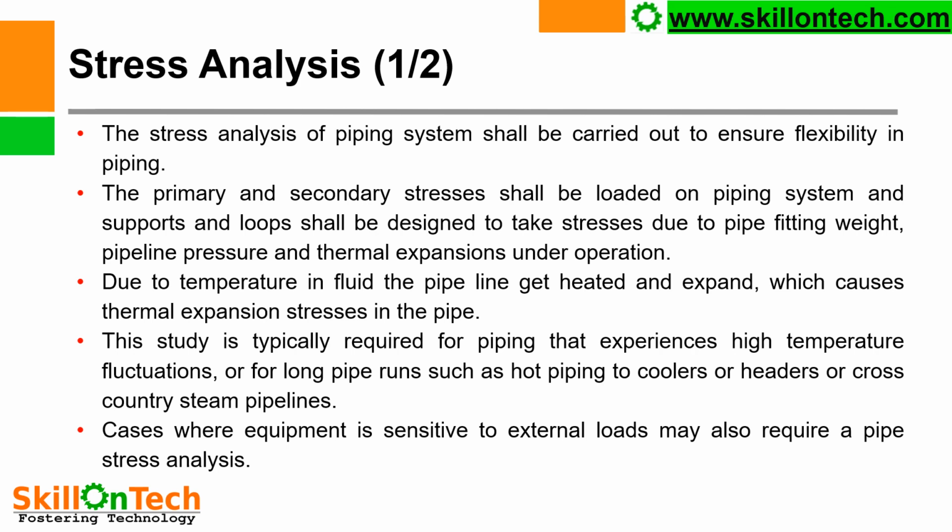So therefore, if cross-country steam pipelines are not provided adequate supports and stress analysis is not carried out, then your supports can fail anytime, and you will not be aware of what has happened in your cross-country pipeline.